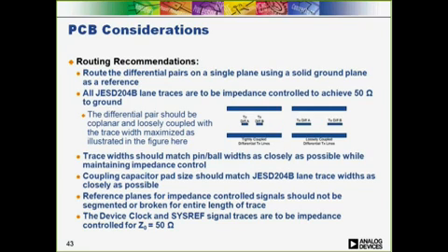Before talking about routing, one thing we need to keep in mind is that while minimizing insertion loss is important, it is even more important to minimize return loss by minimizing the number and magnitude of impedance mismatches along the routing path. Remember, we can compensate for some amount of insertion loss, but all other losses must be managed by good layout and routing techniques.